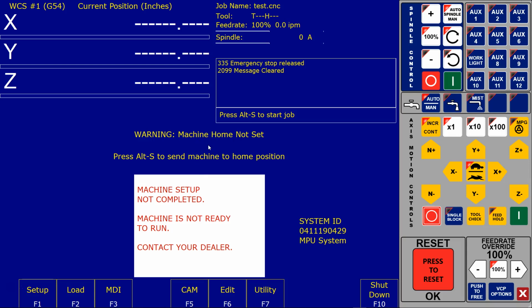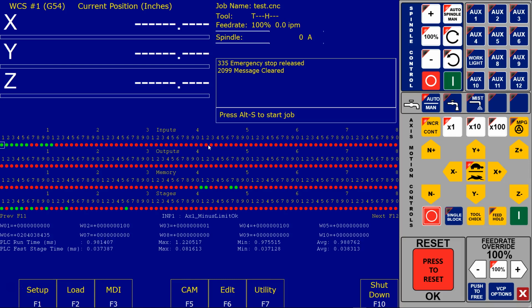All right, so now let's bring up the PLC diagnostic menu. Once again, hitting Alt and the letter I. Now we're going to go to OT6. We're going ahead and flip that switch. And you can see now that that output is turning on based on the state of that input. Okay. Now, as of right now, this is my input being in an open state, I'm flipping it into a closed state. All right. And when I flip it into a closed state, input 16 is green.